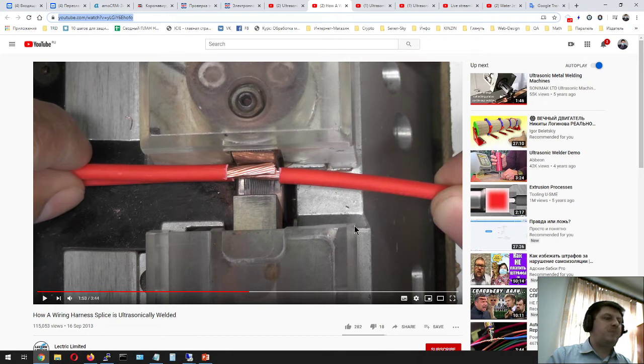It's the process where you put some energy inside the forming area, and you put this energy using ultrasonic vibration, ultrasonic waves. So in this case, for any deformation that you obtain in this forming area, you will spend less power, less energy, because the ultrasonic vibrations help to deform the little particles and the crystal layer too.